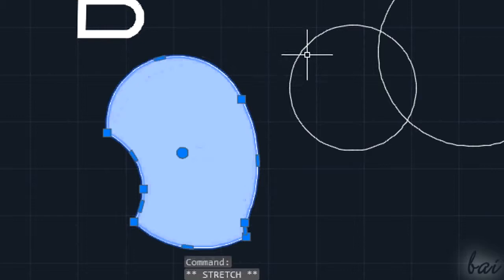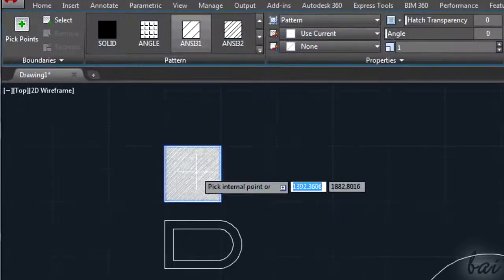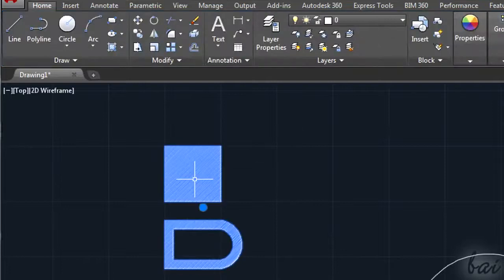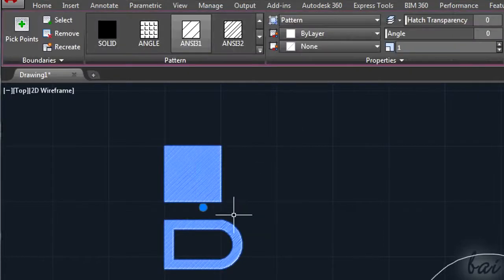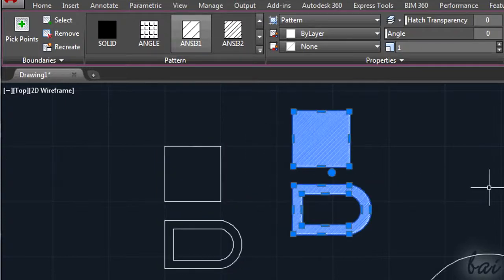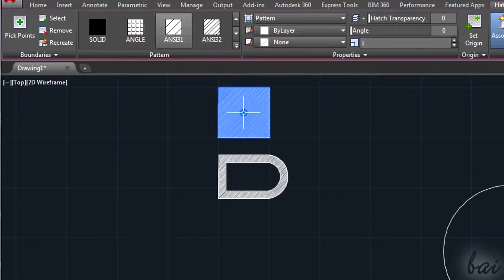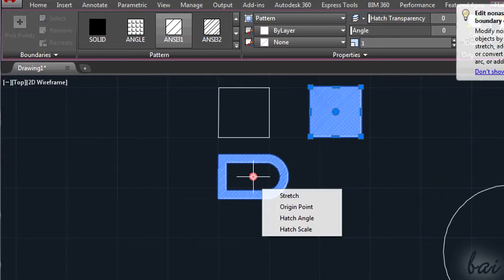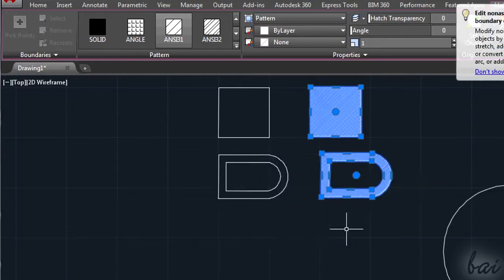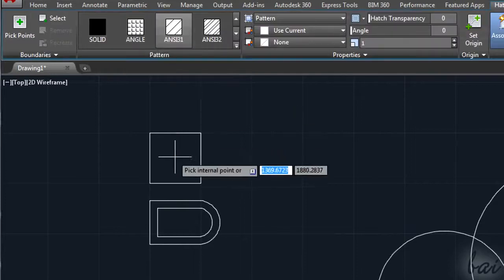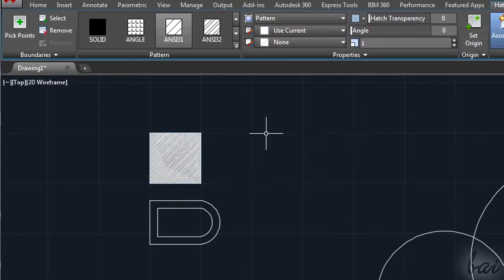Remember that each time you use the Edge tool, a single unified pattern object is created, and this is moved and edited all together. To create single patterns, all independent, you may need to activate the Edge tool for each single pattern. So you need to activate the Edge tool, create the pattern, and then press Enter to exit.